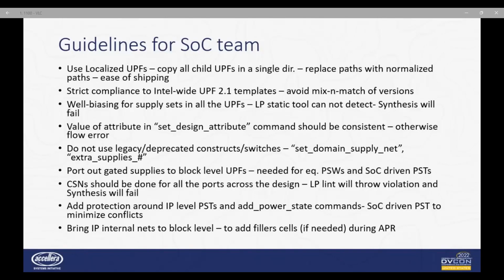Also, all these IP UPFs should be strictly compliant with the Intel-wide UPF 2.1 templates. We were not allowing mix and match of versions. We have seen issues in the past when we mixed different versions. Some tools were unable to comprehend the constructs easily. Also, wiring should be done for all the supply nets present in all the UPFs. Even a single miss will cause implementation tools to fail. There isn't any single rule in the LP static check tool to detect this.